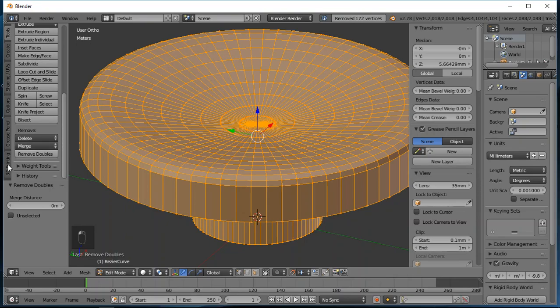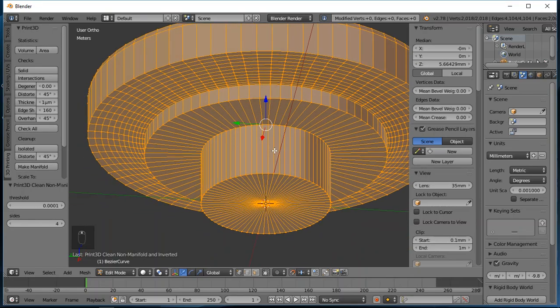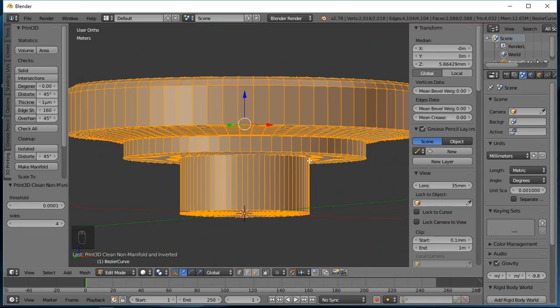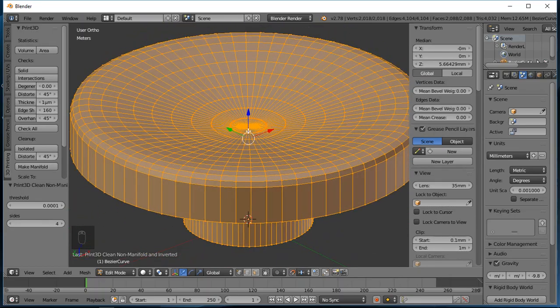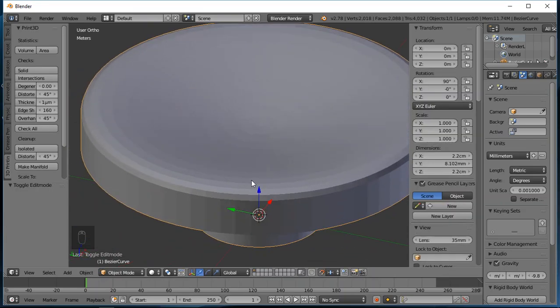One other step in the 3D printing is just to make it manifold. I don't think that's going to be an issue, but just to be sure. And then there's my fidget spinner cap, so it can fit inside the bore of the bearing, step and not hit the face, and then have a nice surface for your finger. So there it is. I won't go through the exporting to the STL or saving, but at this point, this mesh should provide for a good fidget spinner cap.